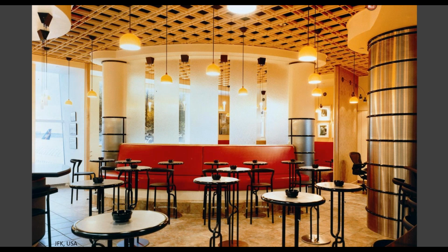So we're introducing our cool air at the floor level, right at the occupant zone, and it's going to pass over the occupants, warm, and then exhaust towards the ceiling and take that smoky discharge with it. And you can see in this ceiling, they actually have a lattice structure that's probably going to some air scrubbers that are kind of pulling the air and then recycling it and then pushing it back down to the displacement units again.